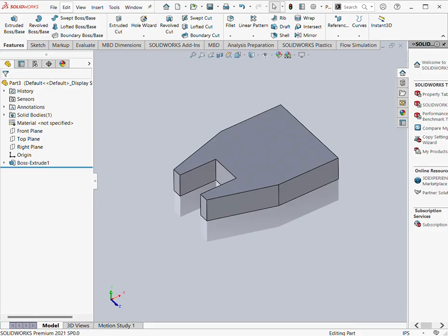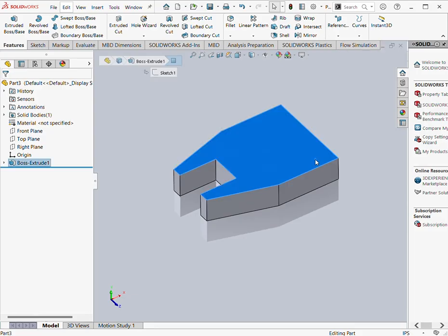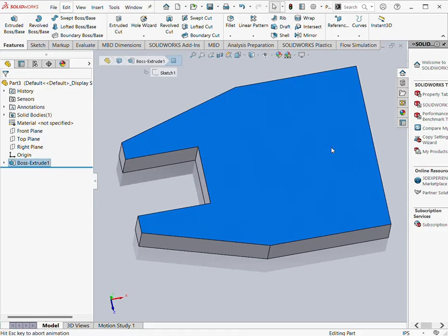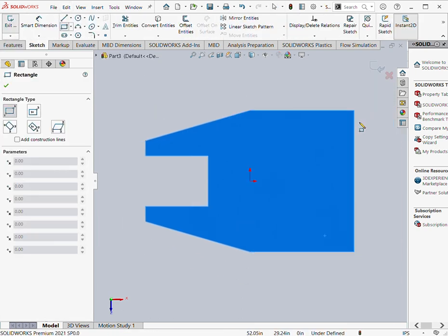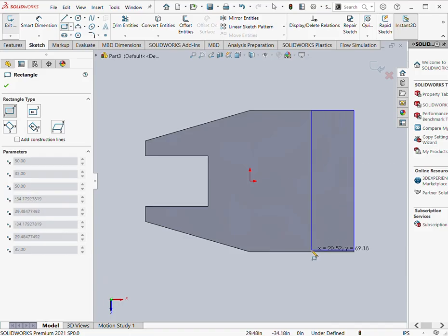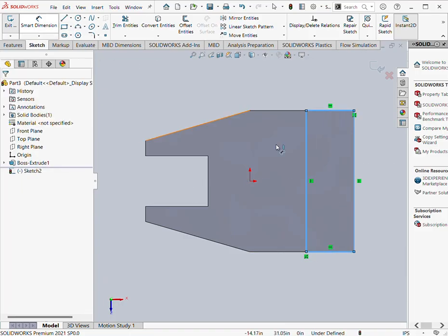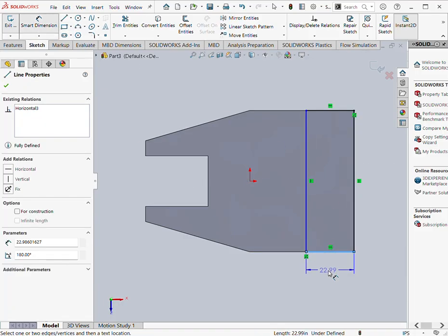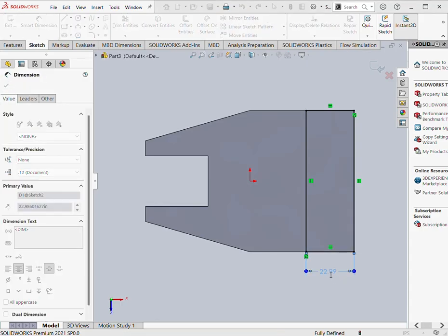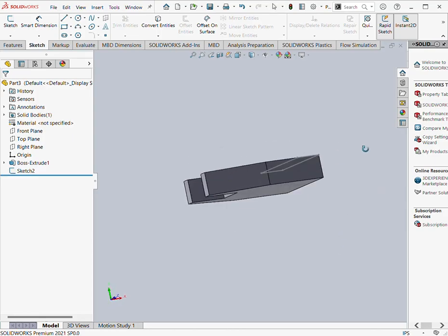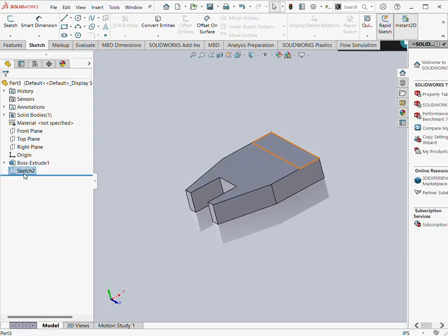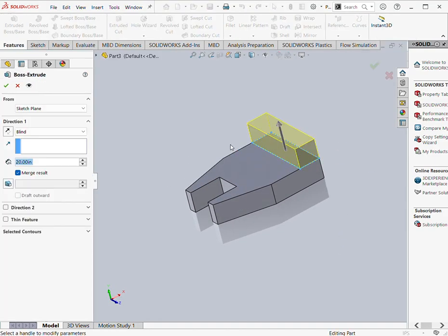Now you need this rectangular protrusion on one side. Choose this face, go normal to it, sketch rectangle by 2 corner and start from this corner up to this edge. What would be the width of this rectangle? 20 units. Length is already defined, so you need only to make a protrusion. How much it should be? 40 total, 20 base already you have protruded, so remaining is 20 units.